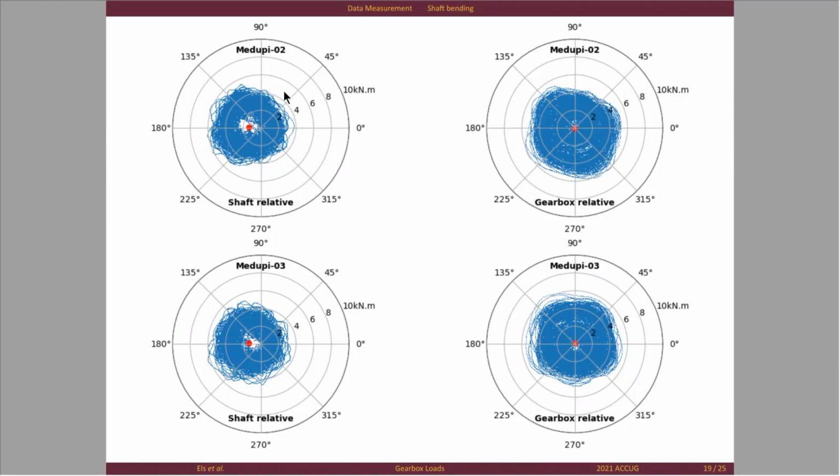That's got a nasty implication for the bearings, for the main bearing at the top, because you can find that the loading zone shifts, which is one thing that bearing people don't want. Hopefully this walking around is slow enough.